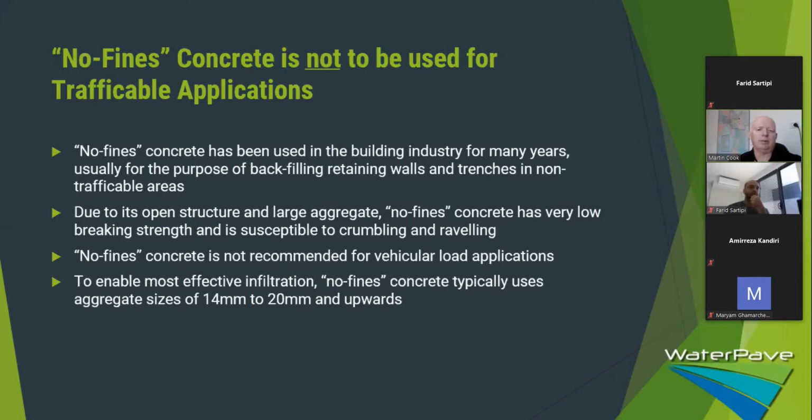As I said, no fines concrete is not recommended for vehicle load applications. It can be used for vehicle load applications when you have a wearing course on the top of it, whether it be a brick layer or a concrete paver of some sort. So when you have vehicles travelling over the top of it, you've got the consolidated strength of the no fines concrete underneath, but you haven't got direct contact with vehicle wheels and tyres to crumble it down.